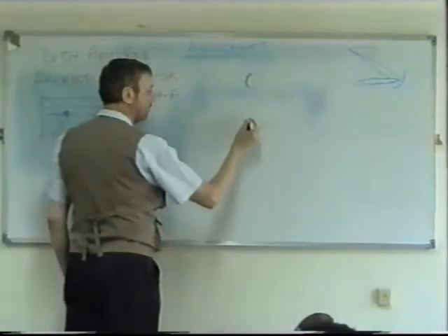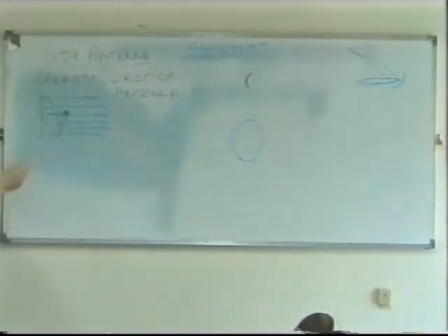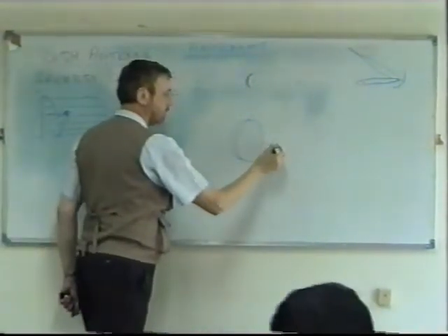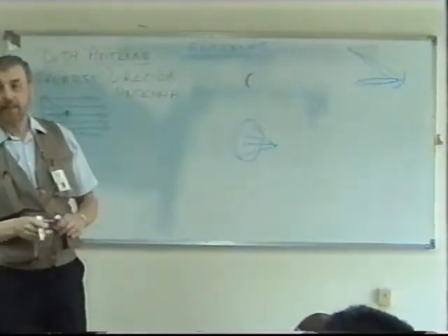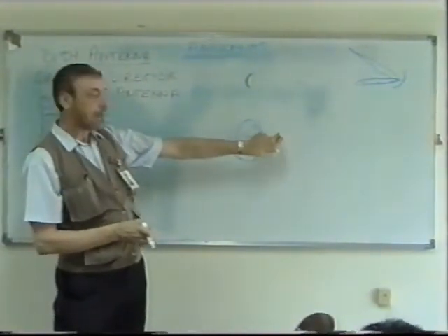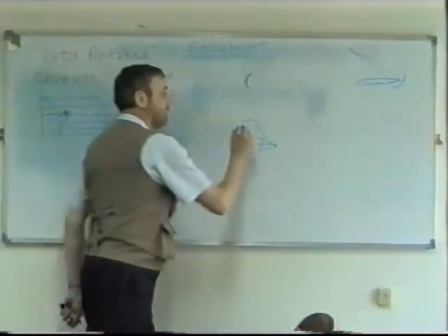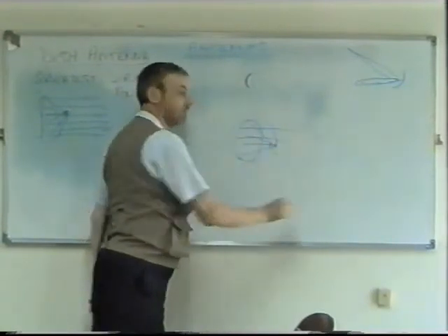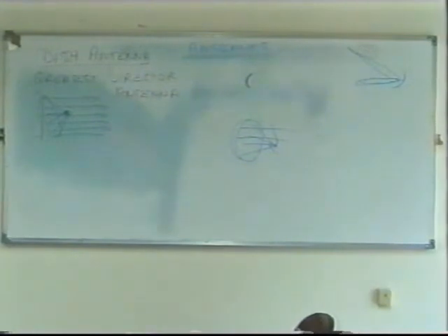All right, we've got a reflector. And don't forget, we've got to have our little transmitter in front of the reflector, here, so that it transmits towards the reflector, and then the reflector can radiate it. Well, there goes our problem. How do we put something in front of the reflector? Because if I put anything physical in front of that reflector, then the waves that are coming from the reflector are going to start bouncing off that thing that I've put in front of it. That's what causes the side lobes.